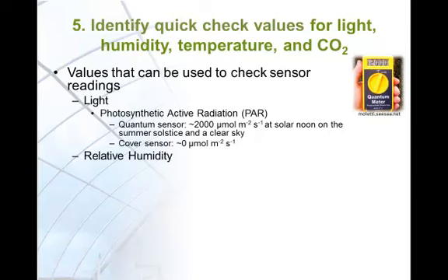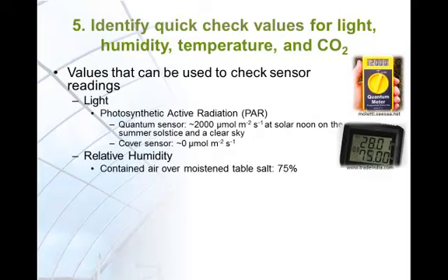For relative humidity, a convenient check is the use of saturated salt solutions. At any temperature, the concentration of a saturated solution is fixed and does not have to be determined. By providing excess solute, the solution will remain saturated even in the presence of modest moisture sources and sinks. When the solute is still present as a solid, there is saturation in the solution.